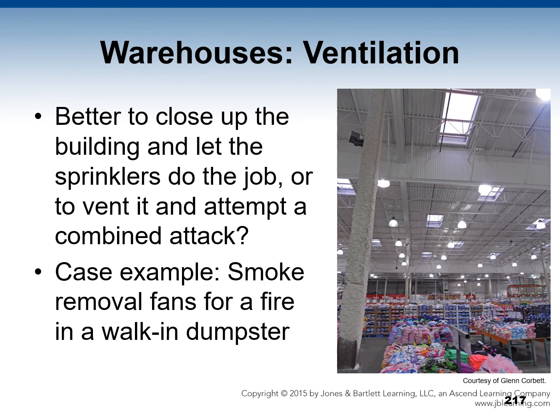When regarding ventilation of a warehouse fire, is it better to close up the building and let sprinklers do the job, or vent it and attempt a combined manual/automatic attack? Partisans of each approach present convincing arguments. One case example is smoke removal fans that were used for a walk-in dumpster fire that filled Sam's Wholesale Club with smoke.